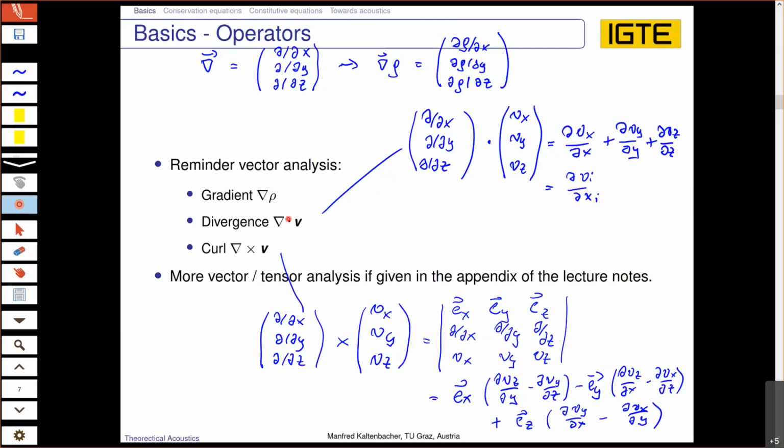We model an incompressible flow by setting the divergence of the velocity to 0, which means for us we don't have any changes in the density. We assume the density to be constant and call such a case an incompressible flow.